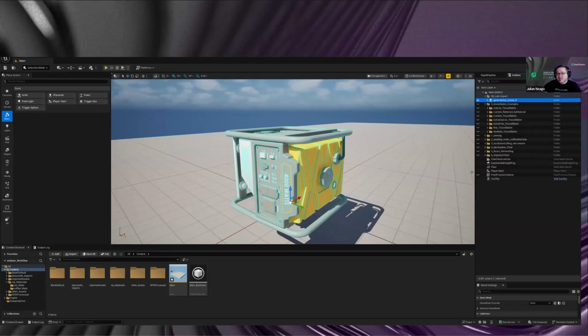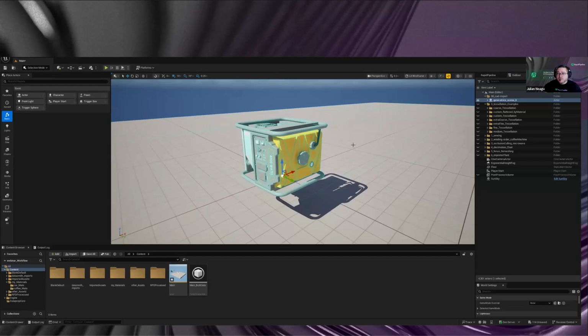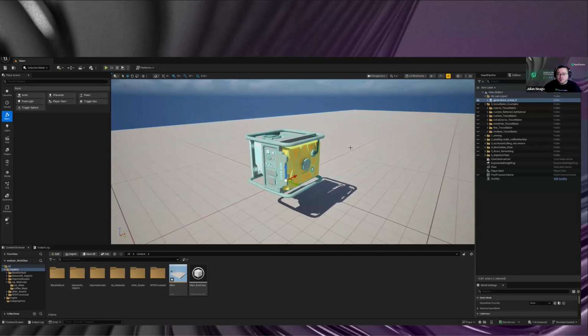The other thing is that it doesn't only populate in your outliner. In order to do that, as you might know as an Unreal professional, your data also has to live on disk, in the content browser. The usual, more old-school workflow would be to load a model in the content browser, check it, go to the mesh tab, go to the material tab, prepare the model if needed, and then drag and drop it, or add it via a script or any Blueprint automation, into your actual scene. In this case, we basically do a little bit of double dipping: we do it in the content browser as well as in the scene.